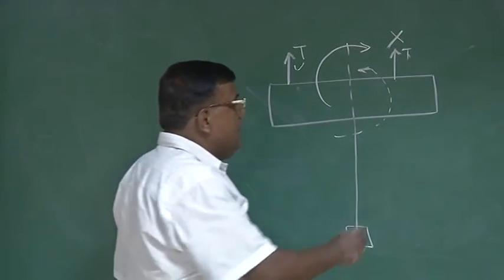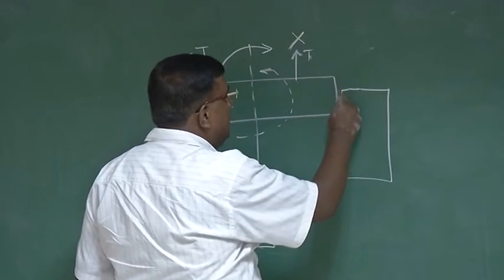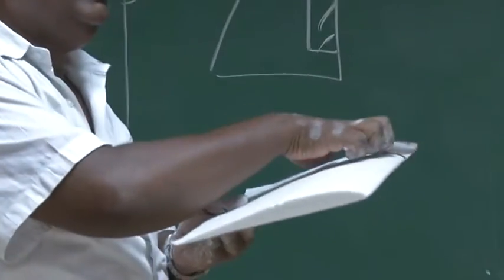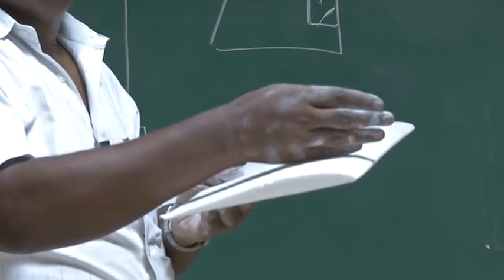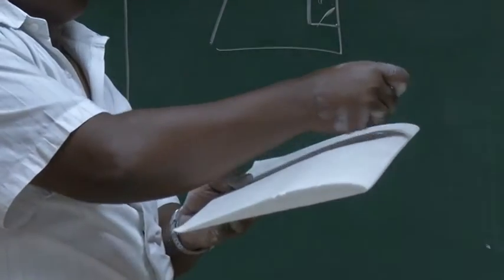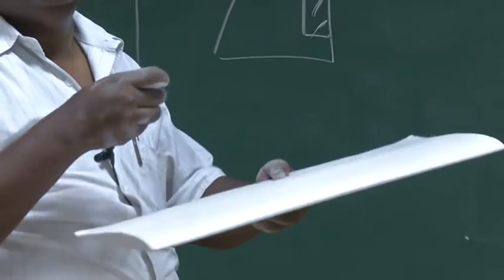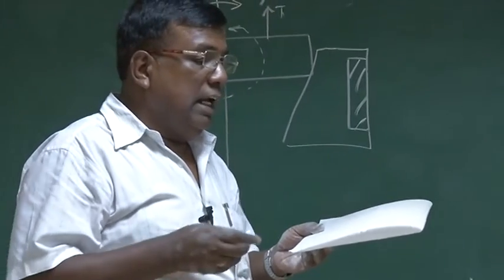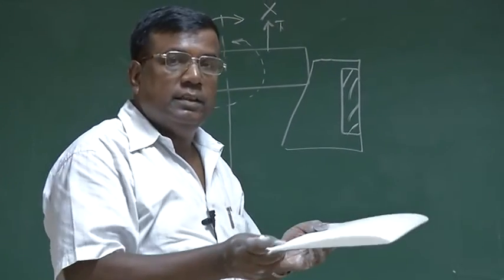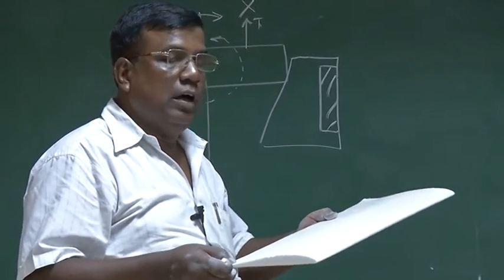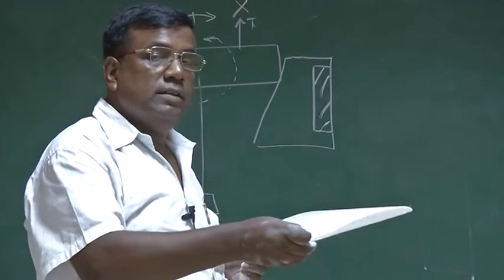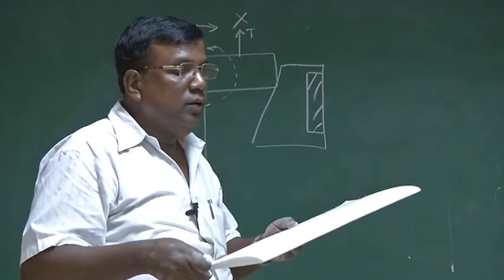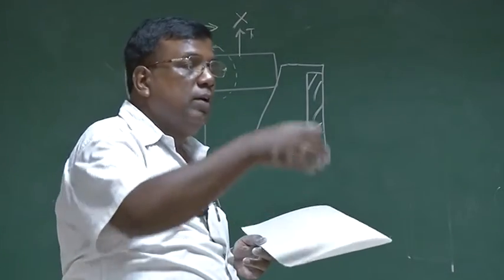Obviously, we have got the rudder, right? You know that? There are two engines, one here and one here. Let's say the right engine has failed. Because this thrust is operative, it will turn the airplane like this on the ground, which will be very dangerous. To ensure that it doesn't happen, I have to generate a moment in the opposite direction. To counter it, I need to generate a moment in this direction. From the top, because of this thrust, a clockwise moment is coming, so I have to generate an anti-clockwise moment when I look from the top.